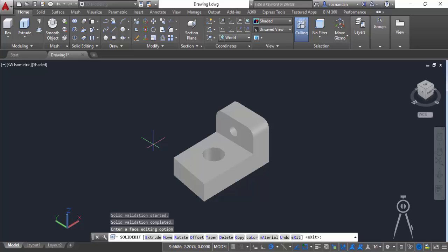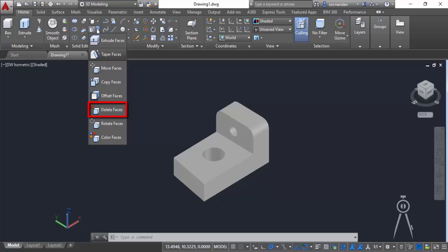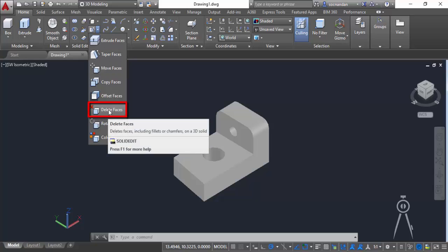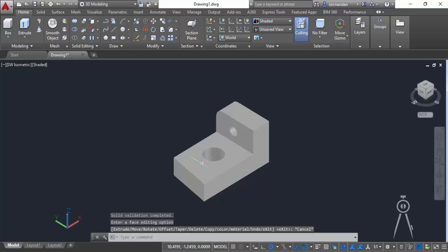You can also remove faces. So in case of this circle, we cannot delete the feature, but using remove faces, we can delete features selectively from the geometry. For example, we can remove the circle or this fillet. Let's do this by the help of delete faces that can be used for removing it. So let's select delete faces. Now let's select this fillet and press enter. And here we have the geometry without the fillet. The fillet is deleted.